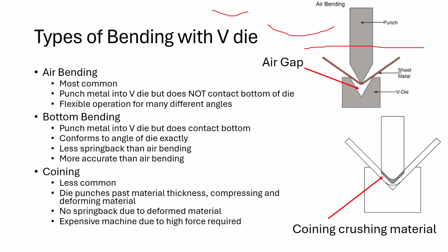So this goes back to why we don't really have the most accurate formulas for these kinds of things. We do have them, but they're not the most accurate. The thickness, the grain size, the distance of this punch, the opening of this die right here. So many factors go into what the final angle is going to be, because we can imagine if this opening was much wider, we're going to get touching the parts here and here. It'll be a little less bend per stroke down.